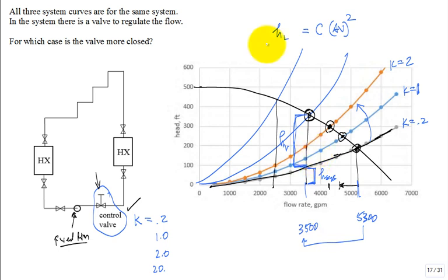But look, you could see that head loss is high, and almost, what is that, 4/5 of it looks like visually is across the valve. So the energy you're putting into this pump, 4/5 of that energy is dissipated across the valve. That doesn't seem very wise energy-wise, does it? You see this? And so 1/5 was used of that mechanical energy that the pump put in to push it through the rest of the network.